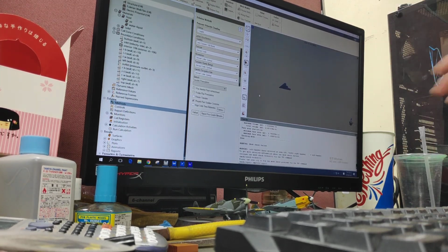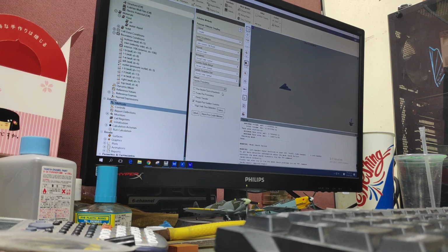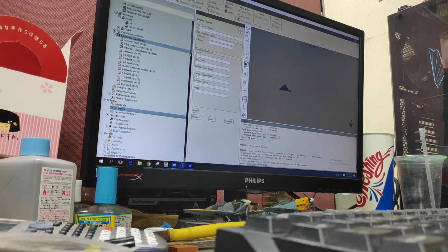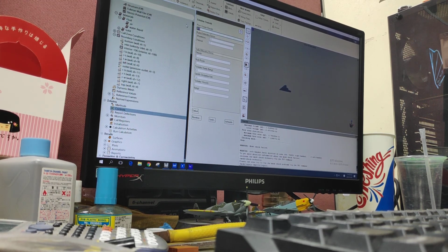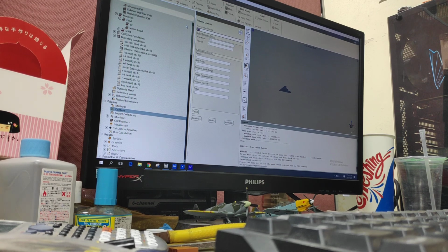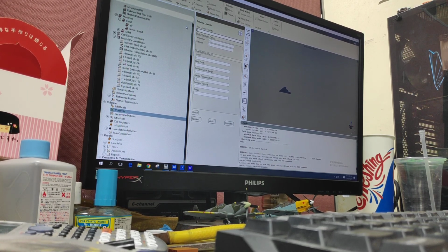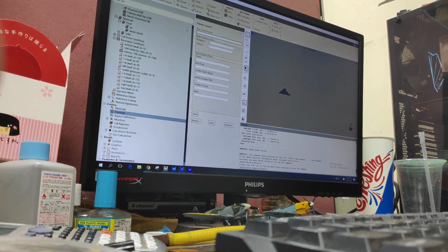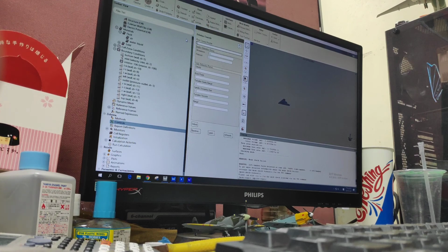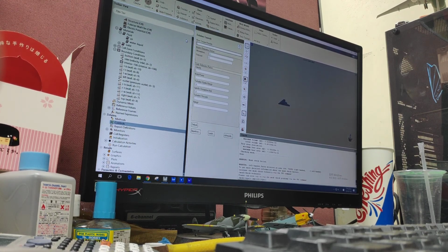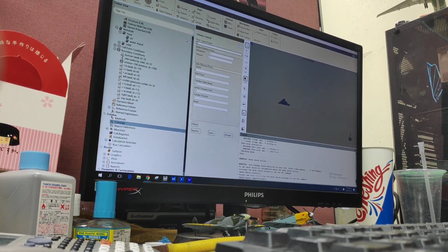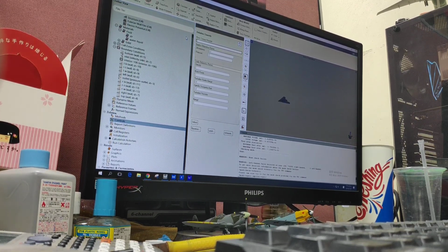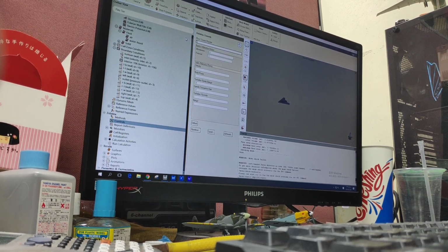Okay, we are done with this one. Go to control. Flow courant number, let's just use 5. Flow courant number set to 5 is the safest number for most cases, but sometimes if you have some problem in your case, maybe you have to change your courant number.